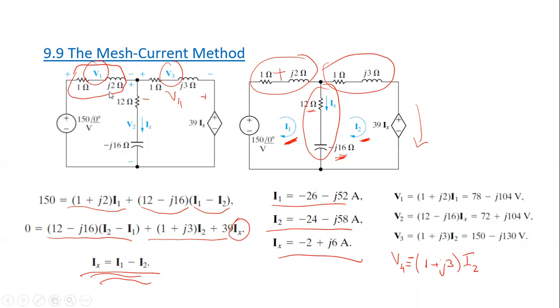So simple. And as you see here, the given polarities were given in the same direction as the current, and this is the current for I2. So you see I plus, I minus, so you don't need to reverse the sign. But if I give you a voltage which has a polarity which is not in the same direction as the current, then of course you need to add a negative sign. Okay. Any questions on this example, please?